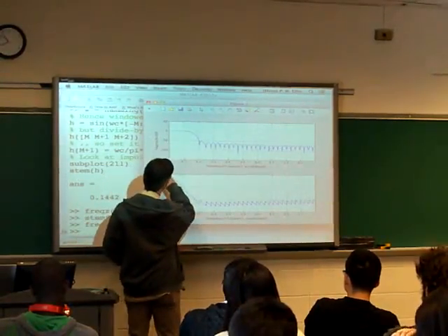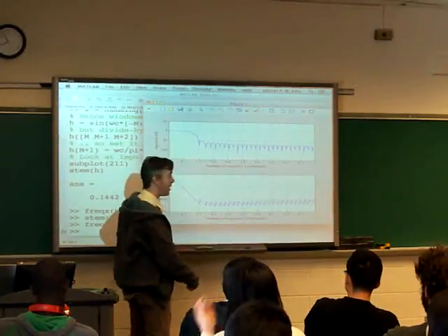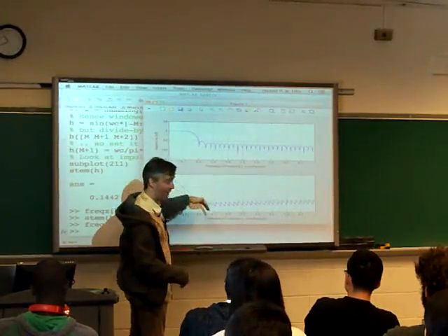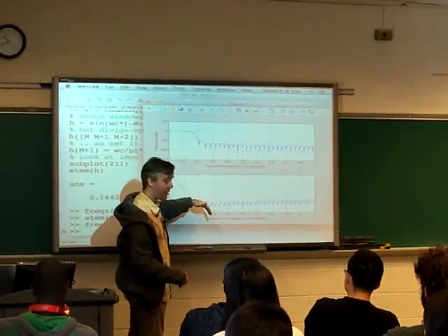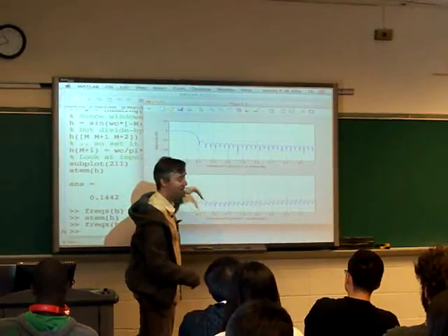Basically, the right way to understand the phase response is just a straight line like this, with a slope in this case of the delay. The length of the filter was 65, so the delay is 33 samples. So this slope is minus 33.